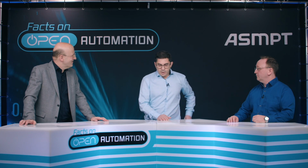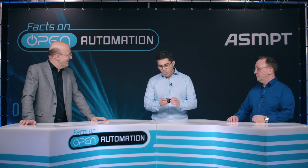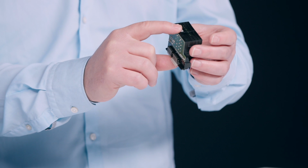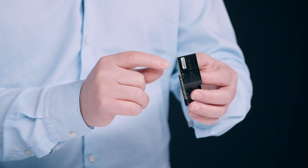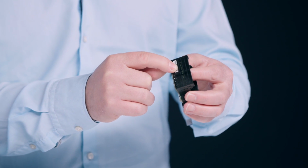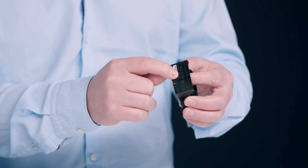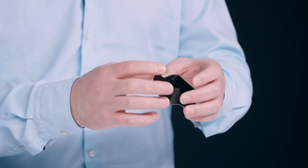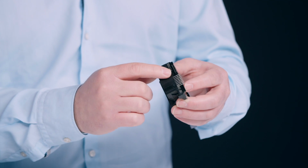Do you have an example for us for this? Yes, Laszlo. I have brought one connector with me. It's a very tall one, 50 millimeters tall. It can't be picked up with a vacuum nozzle due to the pickup surface, so we had to design a dedicated gripper for it. And the next challenge are the pins.